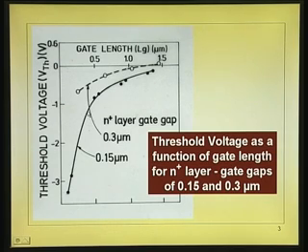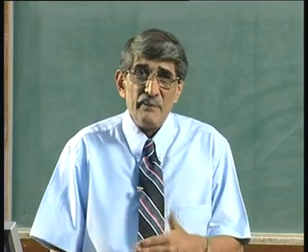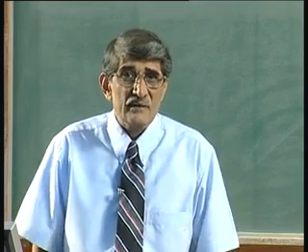And that becomes more and more predominant if the gap between the n plus layer and the gate is smaller, because then the channel length becomes smaller, fields become higher. So, the two dimensional effect becomes much more dominant. Because of that, 0.15 micron is rather dangerous to use, and 0.3 micron is more acceptable. You can overcome this problem further if you increase the field in the vertical direction compared to the lateral field. You can increase the field in the vertical direction by increasing the doping accompanied by reduction in thickness, so that pinch off voltage or the threshold voltage remains the same.